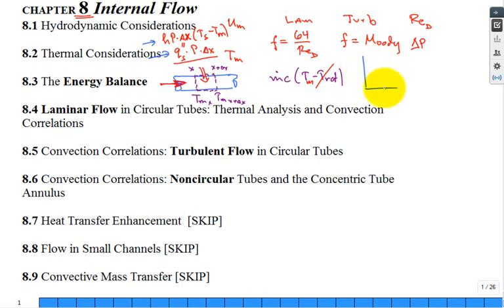especially for if I plot the temperature as a function of location going from 0 to L, and I have a constant surface temperature, T_s of the wall is constant, and I come in cold fluid, T_m coming in as low. What is my equation, analytic equation? It's a kind of boring exponential. And what was our equation that we derived? We derived that theta is equal to, what is that theta coming in? What's theta? Theta is that temperature difference.